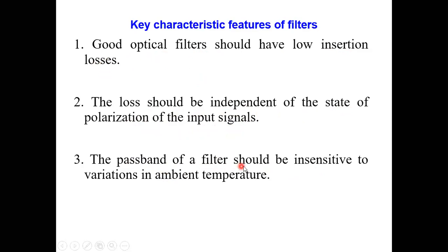The passband, you talked about the passband. Okay, it should have a sharp, selective response. That is good. But when I'm talking about optical filters, it should also be insensitive to the variation in ambient temperature. So apart from sharp, selective, attenuation slope, it should be good. We have to say that the passband of the filter should be insensitive to variation in ambient temperature. So that is one of the points. The way you said your answer is right, to it add all these points.